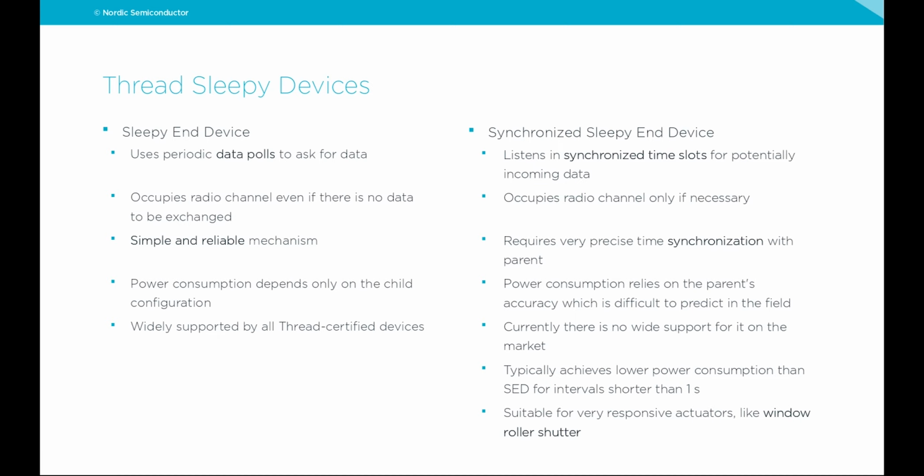Sleepy devices are widely supported by all Thread certified devices, and synchronized sleepy devices are not that widely deployed yet. So it may happen that the Thread parent you have at your home simply will not work with this device well. To sum up, synchronized sleepy devices have some use cases that make it worth using.